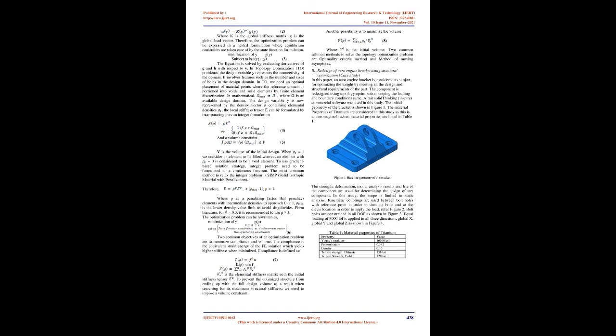Minimization of g(y, z(y)), equation 1. A state function h(z, y) represents the state variable that can be introduced, for example, displacement in a particular direction. For a finite element problem, nodal displacements are solved for in equation 2, where K is the global stiffness matrix and G is the global load vector.